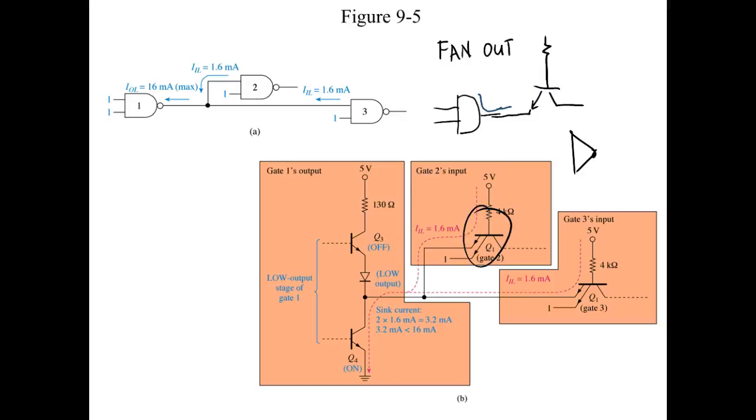What they're doing there is drawing the input. This is the basic input of a NAND gate, but they've got this input connected high all the time, so it's going to act like an inverter anyway, right? Understand that? So when we output a high, then this guy right here is going to take so much current to turn this transistor on, right? You understand that? And then this would be listed as I_IH. Now, this current flow is going to come into this guy.